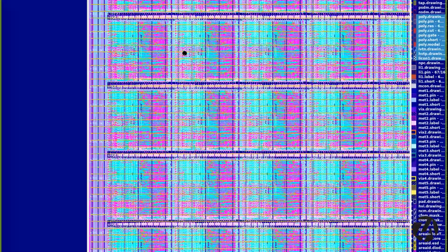They had to build the RTL for these blocks, make the test benches, get the functional simulation, the gate level simulation, the end-to-end simulation with Caravel, and they had to think about how they trade performance with cost in terms of area, for example when deciding how to do decoding for the SRAMs, because an FPGA SRAM, like a memory tile, should be configurable by the user as, you know, a 32 by 8 or a 64 by 4 or something.